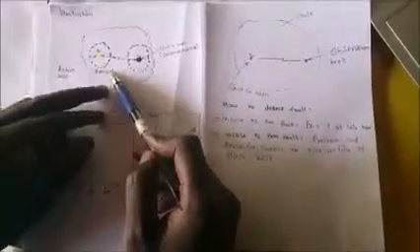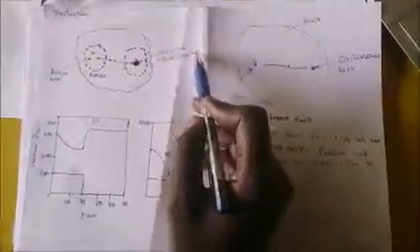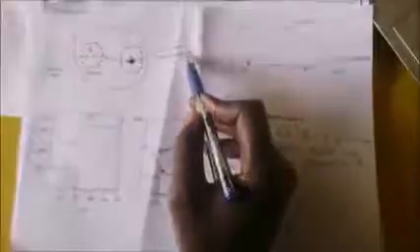In this active well, we are producing at a constant rate, R. Then we have the shut-in well, which is a distance r away from the active well. In this shut-in well, we are going to observe the pressure response, using the pressure gauge. So we record the pressure response in the shut-in well.